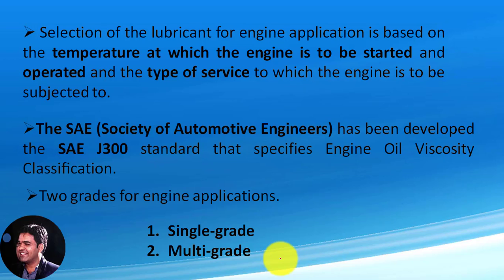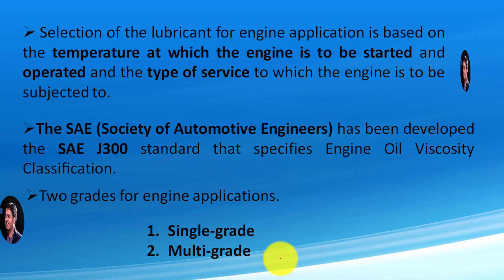This SAE J300 standard emphasizes the engine oil viscosity classification, and on the basis of the viscosity, the SAE prescribed two grades for engine application. One is called the single grade engine oil, the second is known as the multi-grade engine oil. So let's discuss each one step by step.